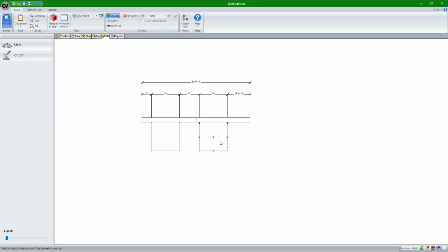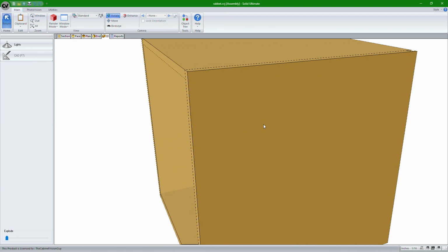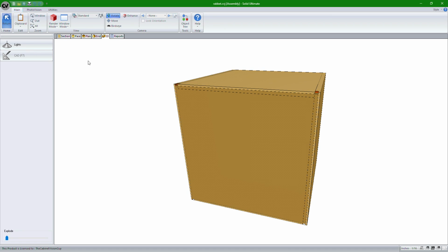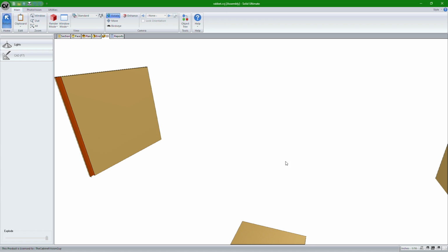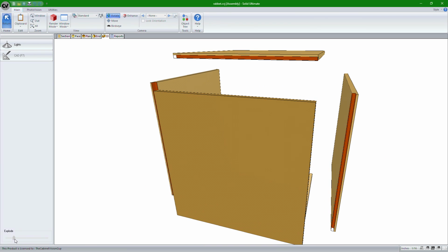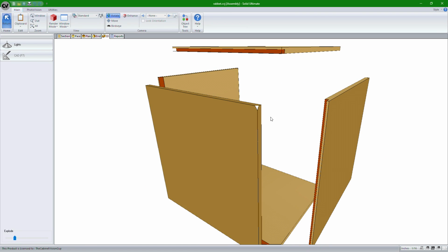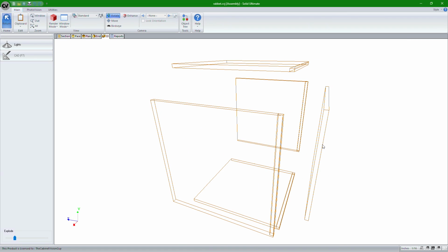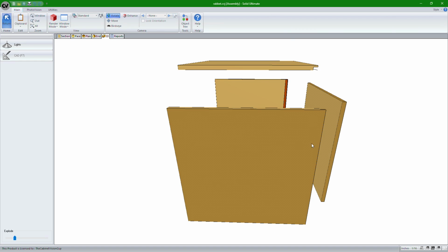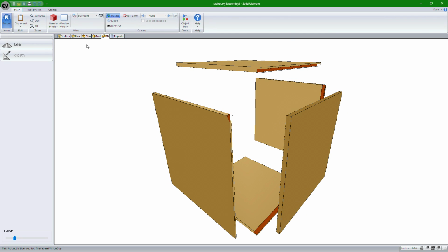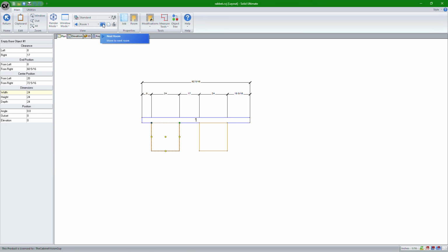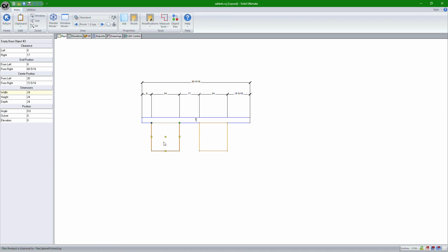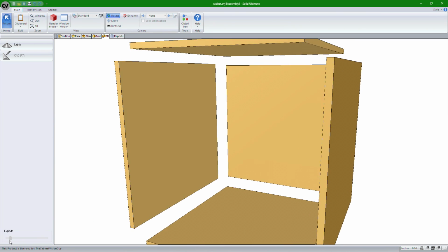Conversely, I went over here and I did the same thing, well, something similar, but instead of putting the operations on the back, I put them on the part. So I created dado operations on the parts there, so I could get through dados without going over any. So yeah, those are just a couple of ways that we can do it, and let's go through how I did that. So go to the copy of the room that I made, which has basically the same objects in it, just no operations applied to them.